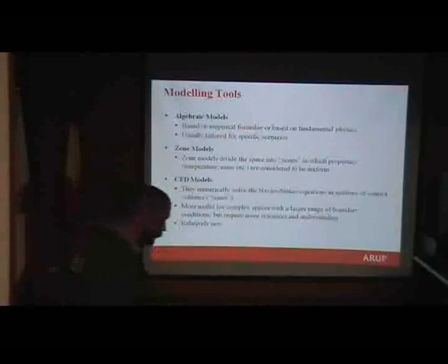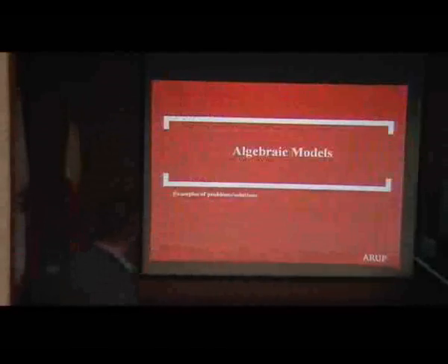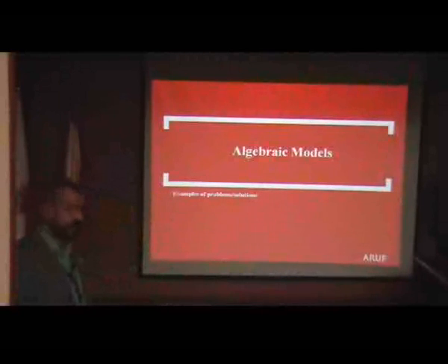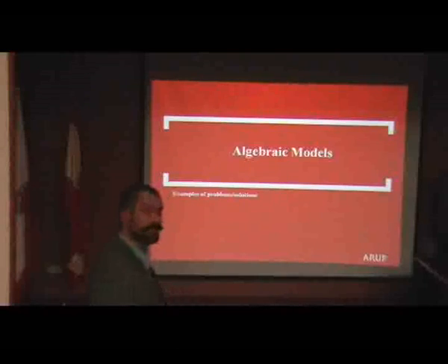The CFD models numerically solve the Navier-Stokes equations in many control volumes, and are more useful for complex spaces like very large enclosures, for example, when the limits of zone models can be exceeded. We start looking at these different models, so algebraic, zone, and CFD. And I'm going to show you some examples. They are just simple examples of problems and solutions, or potential solutions.